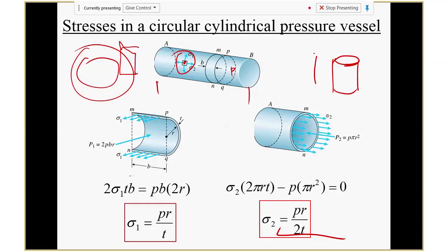In other words, if you have a wall that's not so thin, maybe a thick wall, like an artery, you can still use this to do estimation. What's the average stress? And we're using it a lot, because sometimes for a really thick wall, you can still use it to estimate. Just remember, it's estimation. The thinner the wall, the more accurate this equation will be. So for the veins, because it's so thin, you can use this one to perfectly estimate the stress. But for arteries, remember, just estimation. Okay, so we end up with these two equations.